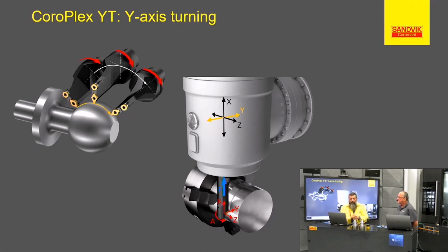If you're running high volume, or if you want insert consolidation, extra sister tools in the chain, or tooling redundancy, it's a fantastic system. This can be a left or a right-hand tool or a neutral tool, and we have 2 inserts on there. One tool, 6 cutting positions without going to the tool change belt.